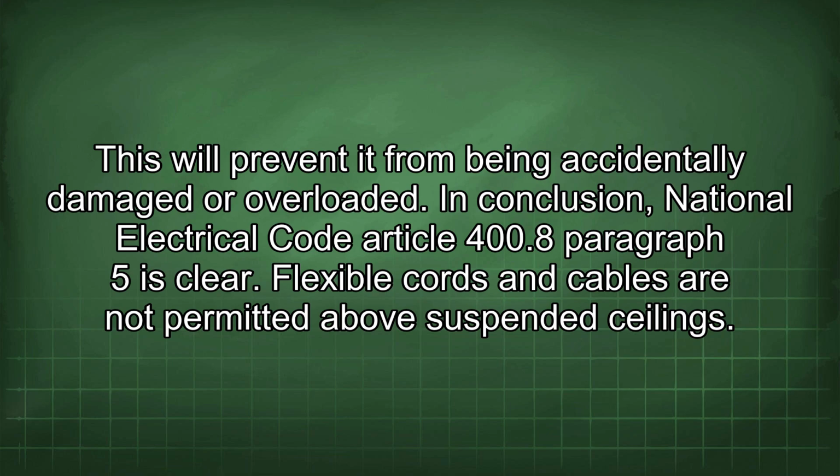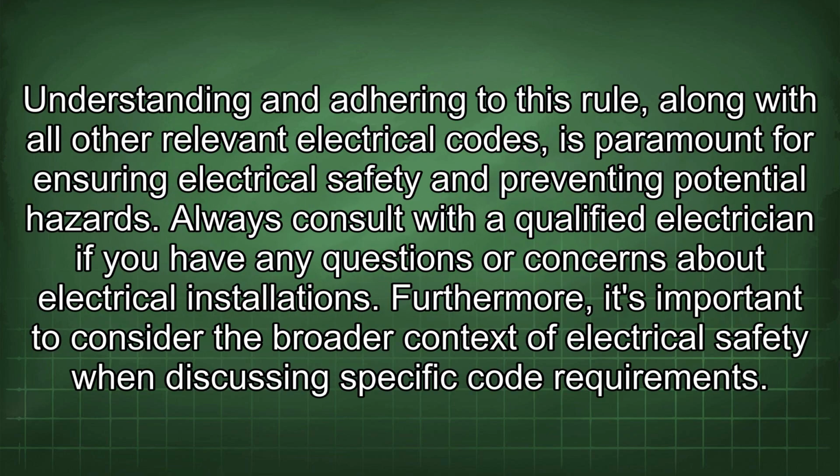Flexible cords and cables are not permitted above suspended ceilings. Understanding and adhering to this rule, along with all other relevant electrical codes, is paramount for ensuring electrical safety and preventing potential hazards. Always consult with a qualified electrician if you have any questions or concerns about electrical installations.